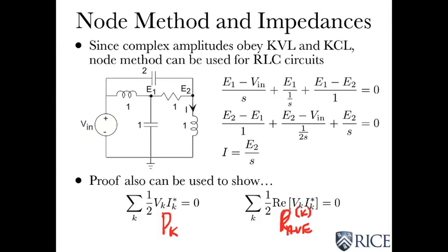The reason is that if you have the KCL equations, and if you just take the conjugates of them, adding up the conjugates of complex amplitudes of current also equals 0. So this shows that power in all senses that we've talked about, complex amplitudes or power in the time domain, all have to add up to be 0. All circuits from any viewpoint satisfy conservation of power.